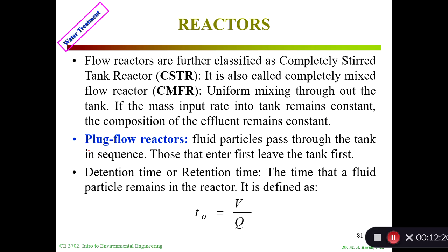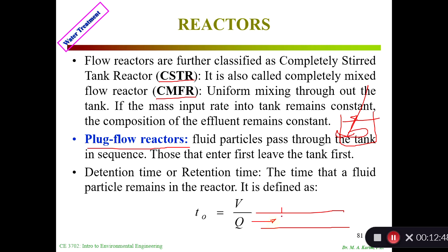There are plug flow reactors. There is also the completely mixed stirred tank reactor, or completely mixed reactor, also called a CMFR. That means if we have a reactor here and we have water, then we mix it. The idea is if we take a sample from here or there, the concentration will be the same. And plug flow is something like that. If it is plug flow, different regions have different concentrations, right? If I take water from here, I'll get one concentration, from here another, from here another concentration. So that's what it is.